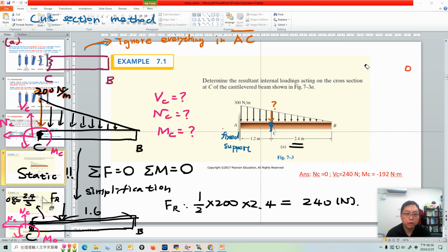Okay, let's start from this. Let's reuse the rigid body equilibrium. Rigid body equilibrium: resultant force is 0, resultant moment is 0. And this is a 2D problem. So, summation Fx equal to 0. Let's see, do we have an X component force? X component, we don't have, we only have the normal force.